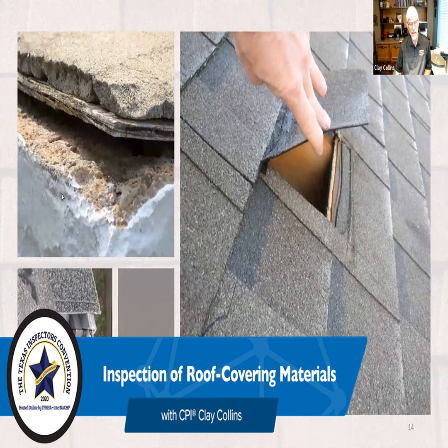There are two things that I've heard from various inspectors. One is that they go on the roof first to see where repairs have been made, so they're able to look closer at the ceiling cover to see if there's damage. And the other is that they look inside, especially at the ceilings first, so they'll know where to look in the attic for leaks or on the roof for leaks.